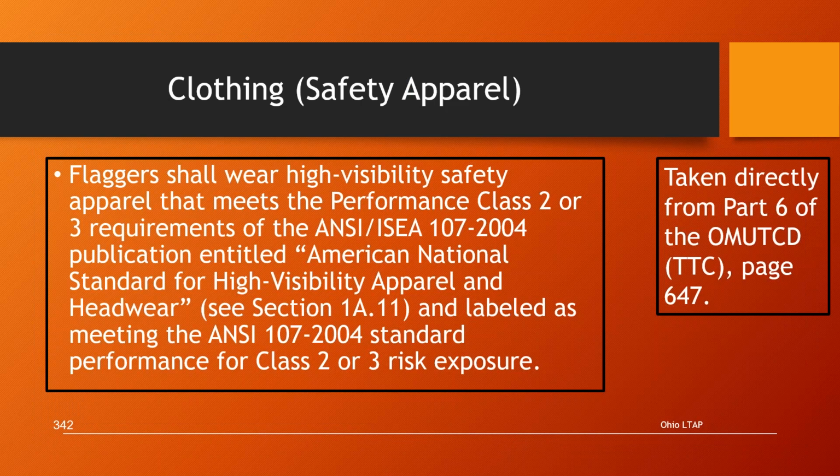I got some information here straight from the manual about the safety apparel for the flagger. You shall wear high visibility safety apparel that meets the performance class 2 or 3 requirements. We just saw a video from the Department of Transportation of Virginia, and they've already required their flaggers to wear class 3 all the time. They don't even mess around with class 2. So if you abide by the state of Virginia's requirements, then you're doing a good job,